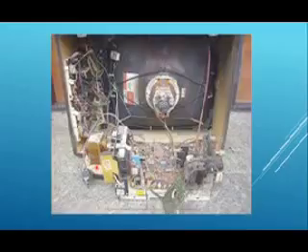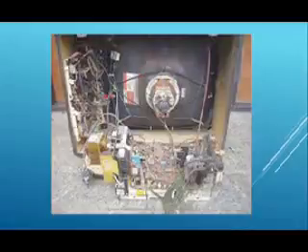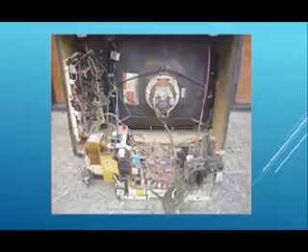the FM sound modulation. To display the picture on the picture tube, special sweep circuits are needed to generate the voltages and currents to operate the picture tube. Sync circuits are needed to keep the sweep in step with the transmitted signal.